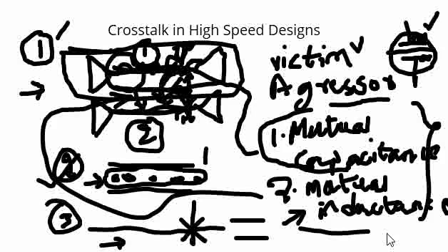Like if there is one line, take another line and move it away from the trace, and again you can move it nearer. This is one technique which PCB layout engineers follow in their layouts to ensure that the signals are not routed parallel over a longer distance. So that is one scenario, right?